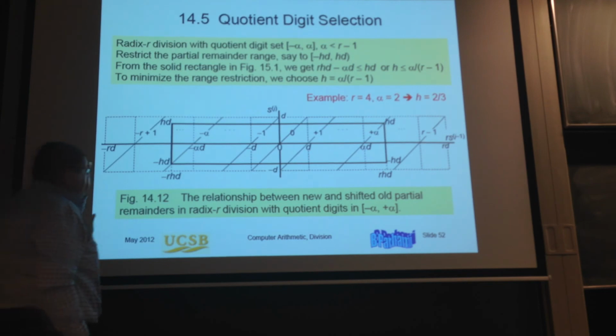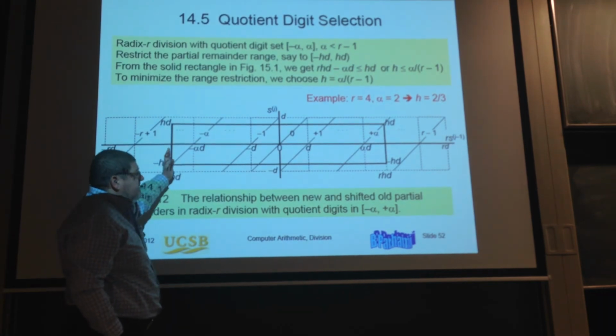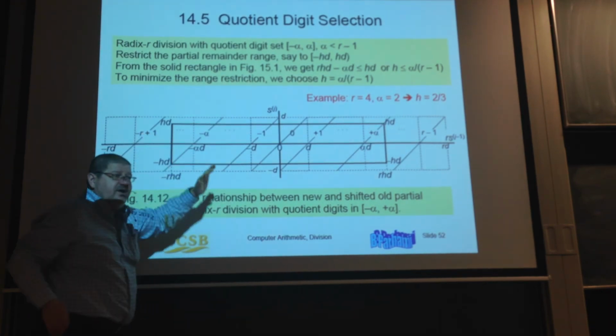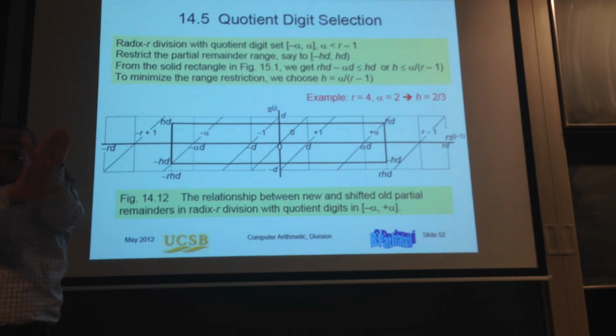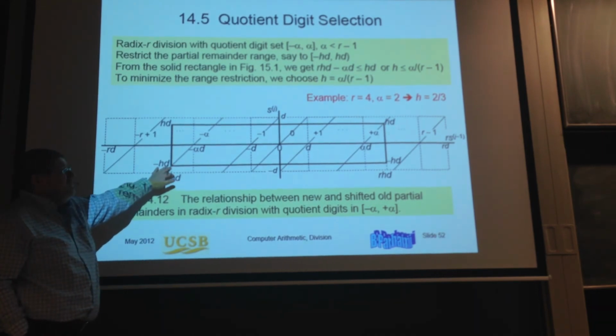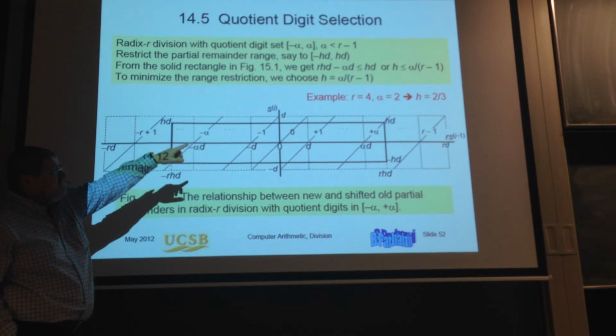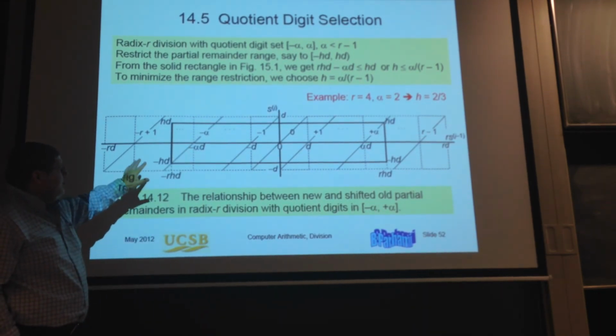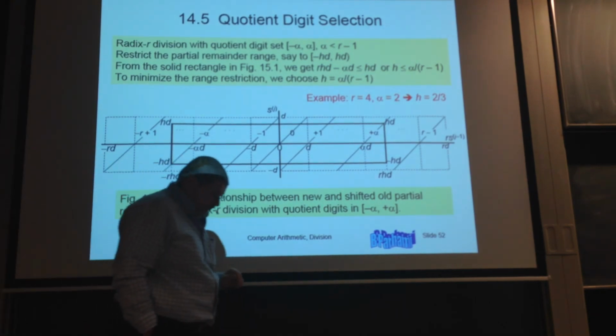Now, if you do that, you may remove some of the choices and simplify that, but as I told you, your lines in the space will get closer, which means your logic will be more complex. Then if you go for a random kind of radix design, you will get such a diagram. You may apply scaling or not. This, for radix 4 scaling, you multiply with 2 over 3, and then you have to make the choice.